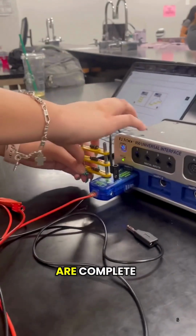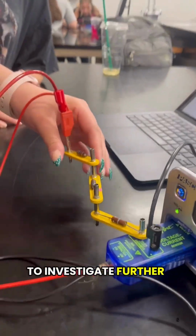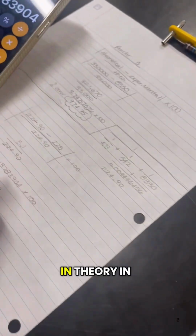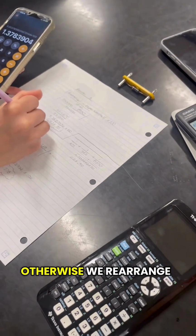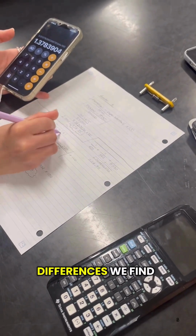Once both tests are complete, we compare our 2 graphs and note the difference in resistance between the series and parallel setups. To investigate further, we explore whether the order of resistors affects the total resistance. In theory, in a purely series or purely parallel connection, the order shouldn't change the result. However, if we believe otherwise, we rearrange the resistors, collect data again, and note any differences we find.